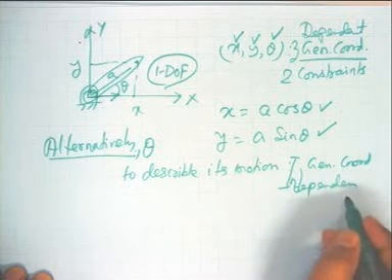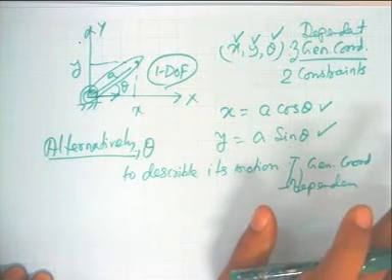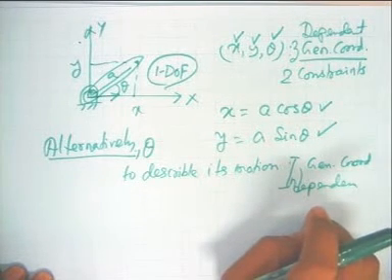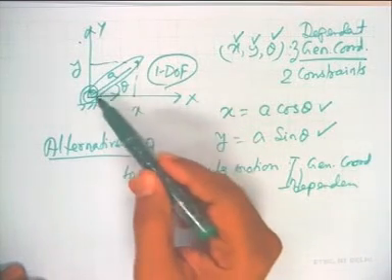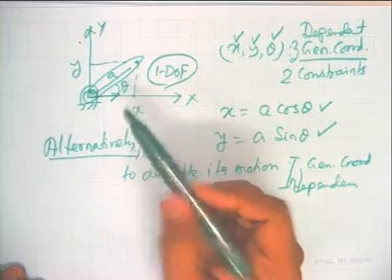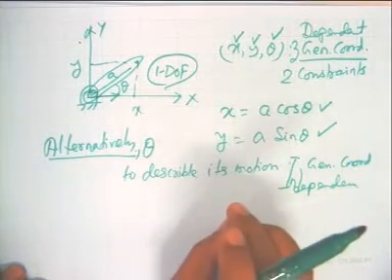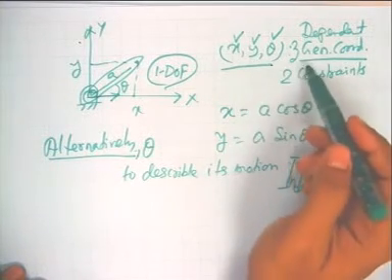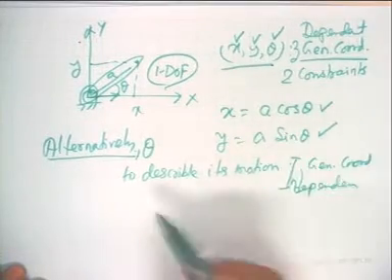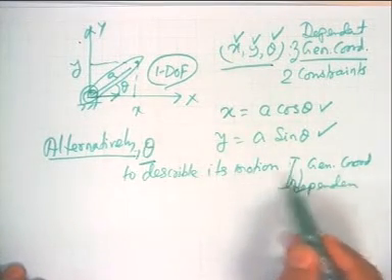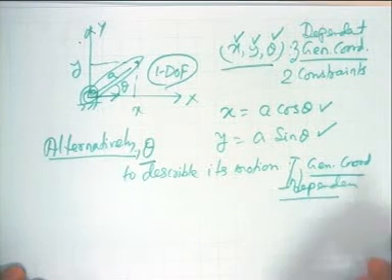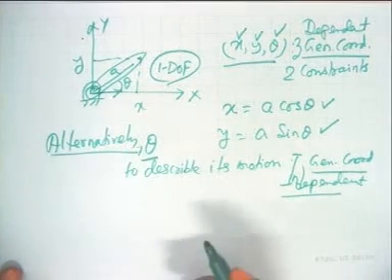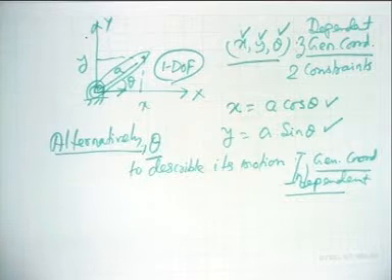Okay. So, this is independent generalized coordinates. This is the concept of coordinates: the number of parameters used to describe the system completely, be it Cartesian coordinates, rotational coordinates, or polar coordinates. Any coordinates which are sufficient to describe it are generalized coordinates. If we use more coordinates than required, we call it dependent generalized coordinates. If it is equal to the minimum number, then we call it independent generalized coordinates. Okay. Now, in parallel to the definition of generalized coordinates, we can also define generalized force.